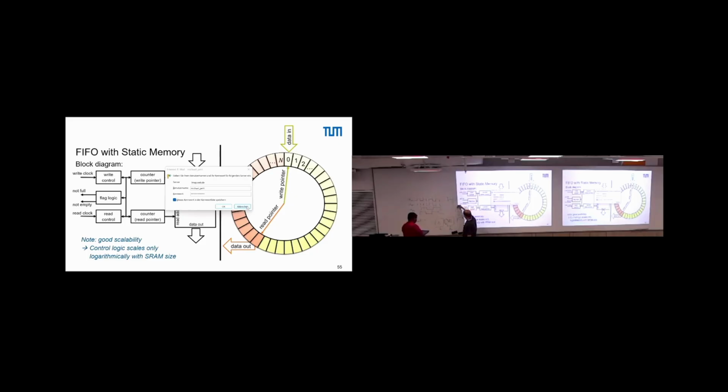And I could also write here, effectively, this is not full, and this is not full, and this is not empty, and this is not empty. So, if the empty signal is reset, the not empty is set, that is an operation triggered by the write domain, evaluated by the read domain. So not empty, but it can be triggered by the write domain. It's not in all cases triggered by the write domain, but in half of them. And full the other way around. Okay?